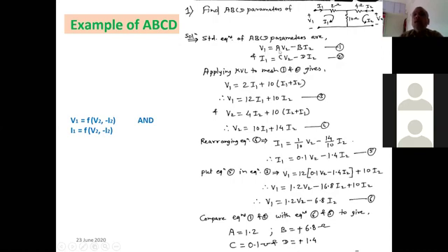Now we want V1 to be expressed in terms of V2 and I2. So in this third equation, it is the equation of V1, I1 and I2. We want V1, I2 and V2. So instead of this I1, it should be V2, I2 and V1. Okay, so this I1 you have found out from the fourth equation. After rearranging, we have got I1 is equal to 0.1 V2 minus 1.4 I2. So substitute this value of I1 from equation 5 in equation number 3.